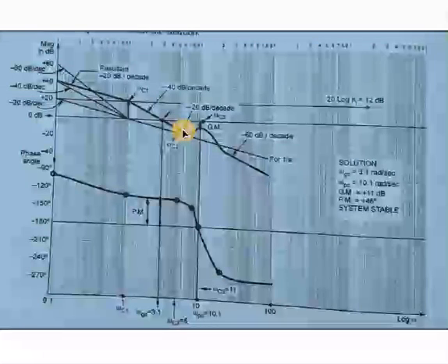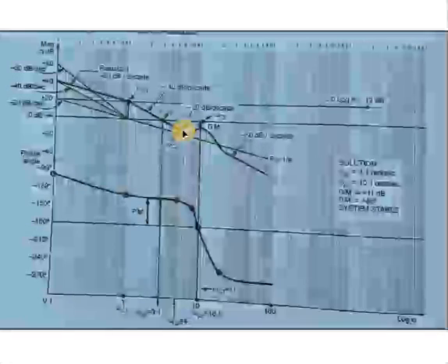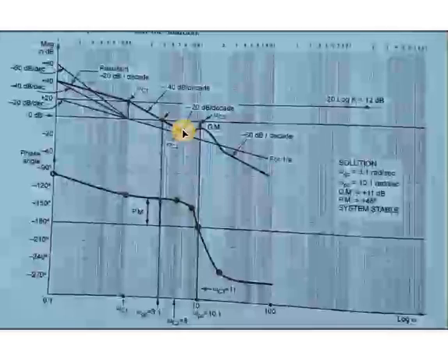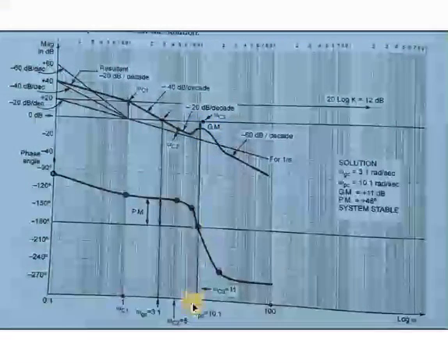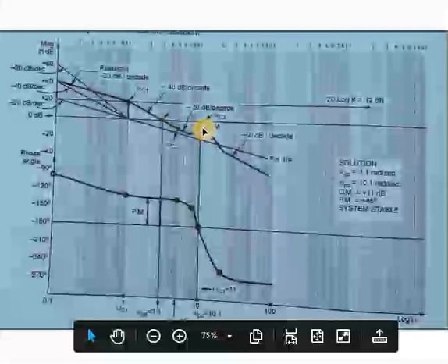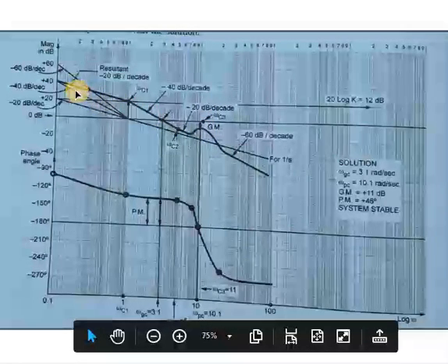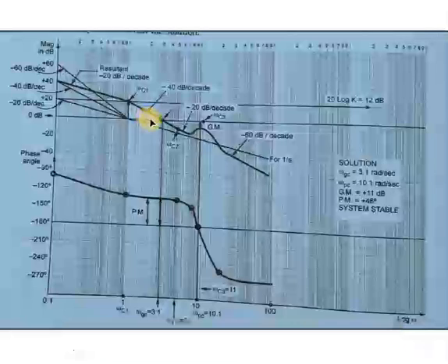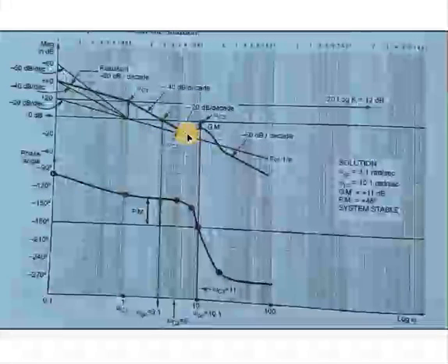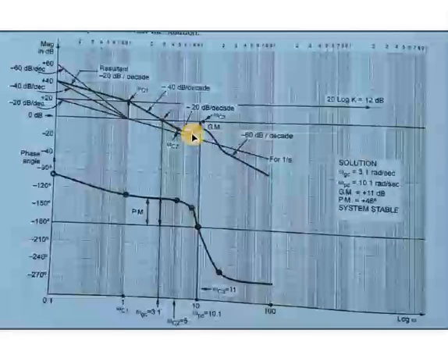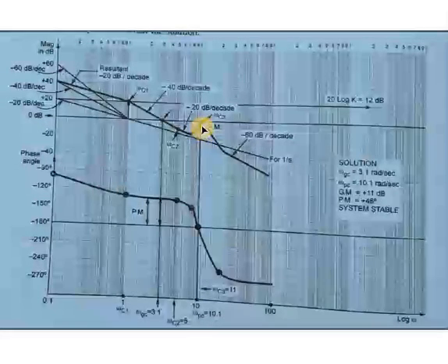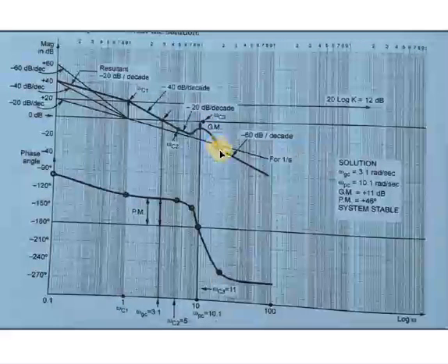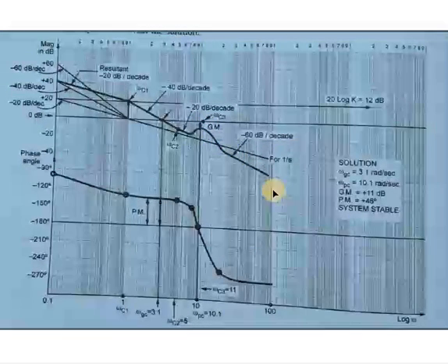You need to calculate that correction factor, and mark it here at the respective frequency value of 11 radian per second. While drawing the plot, you draw as in the normal procedure. Only when you come near omega equal to 11, there you need to give the excitation, where this distance will be 7.13. Then you continue with the respective slope.